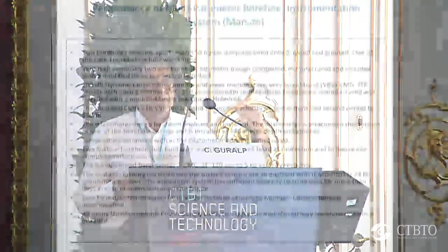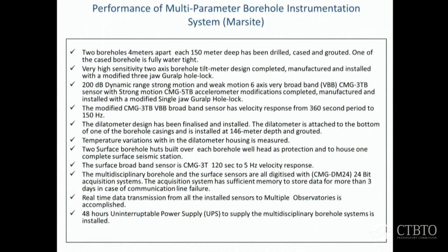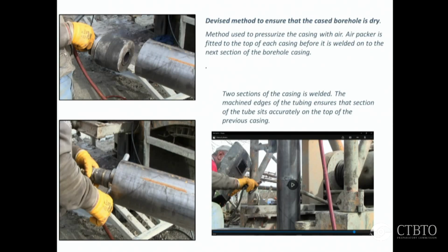But in addition to the broadband instrument, we've also installed a dilatometer. And the design of the dilatometer is brand new in the sense that it's intended to be a high-frequency dilatometer as well as being a long-period one, meaning it's DC coupled all the way from earth tides to creep to the deformation, but all the way up to 30 hertz to understand how a dilatometer compares to a short-period instrument. To show that, I'm just going to literally go through the setup.